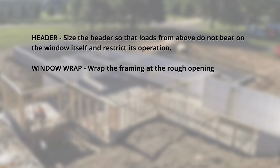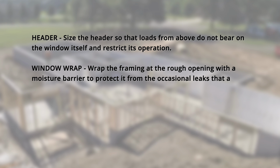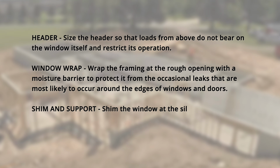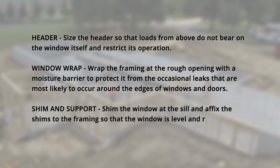Wrap the framing at the rough opening with a moisture barrier to protect it from the occasional leaks that are most likely to occur around the edges of windows and doors. Shim and support. Shim the window at the sill and affix the shims to the framing so that the window is level and rests firmly on the framing.